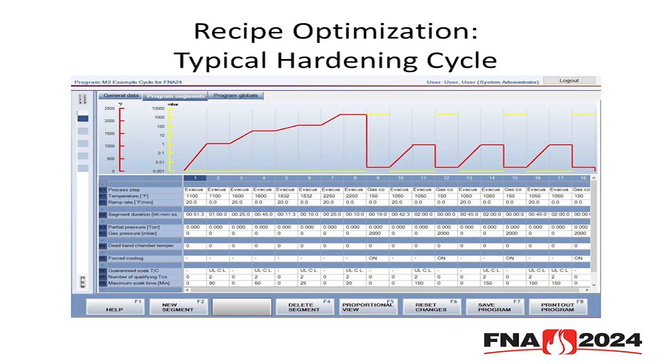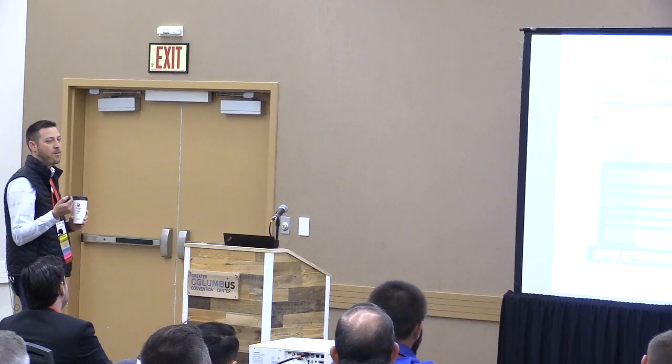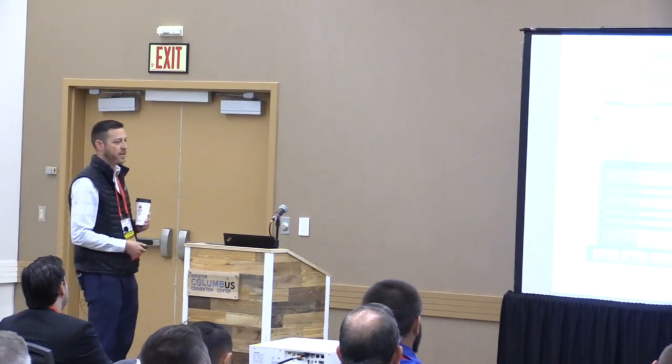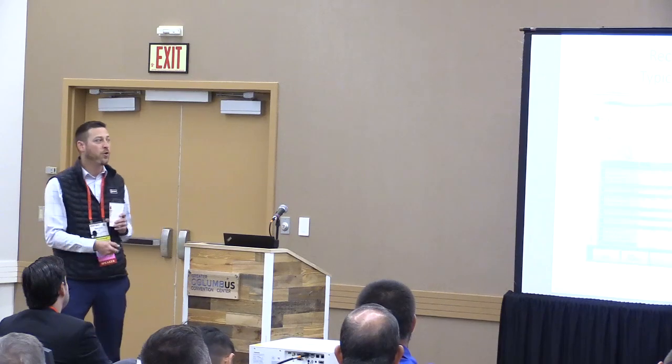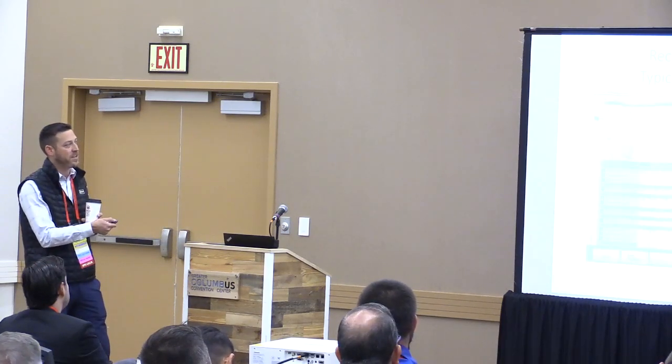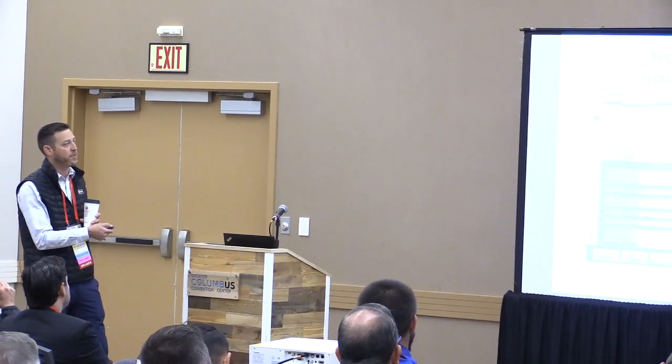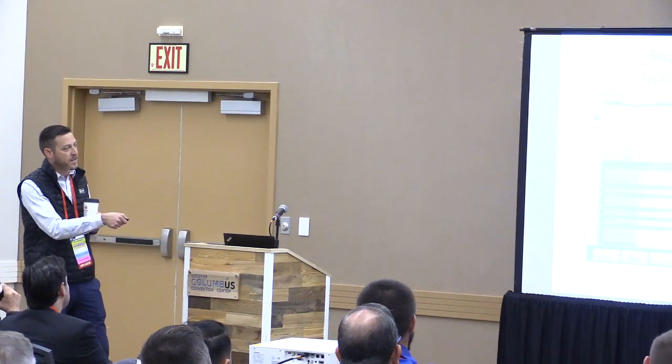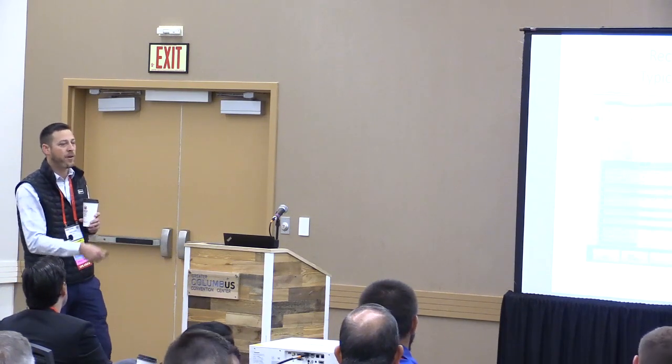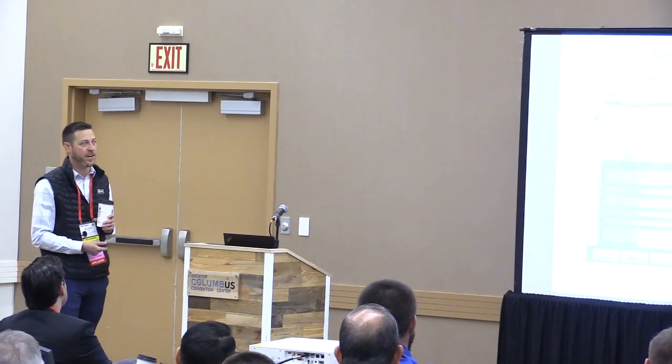But what I wanted to show you guys is, let's say you are running M-series or some tool steels that temper at a high temperature. You could go straight into your tempers in the vacuum furnace right after your hardening process, and you can set that up in a single run. You don't need an operator to come over and check on the parts and then go into the recipe for the vacuum temper and then proceed to do that 3 times.